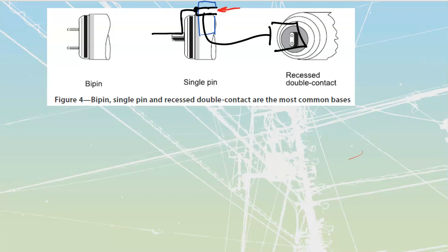So we can get some really dangerous effects where pieces of equipment are fully lit by fluorescent lighting. We're talking about the inside of the bowels of your building, like a machinery room where you have no natural light. If you've got natural light on there as well, you're going to be fine. If you've got incandescent light, you're going to be fine. But where it's just a room that's sealed off and only has fluorescence, you could have pieces of equipment that would not only appear to be running slowly, but could actually appear stopped or even to be running in reverse. And if you're unaware of that, you might do strange things like shove your hand into it because you think that thing is not operating, and bling, there goes your fingers, right? It's a bad time. So we have to be very careful of that.